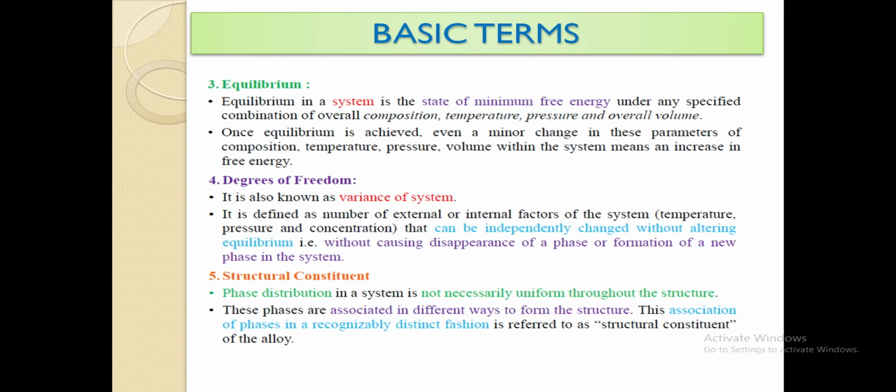Structural constituent. Phase distribution in a system is not necessarily uniform throughout the structure. These phases are associated in different ways to form the structure. This association of phases in a recognizably distinct fashion is referred to as structural constituent of the alloy.